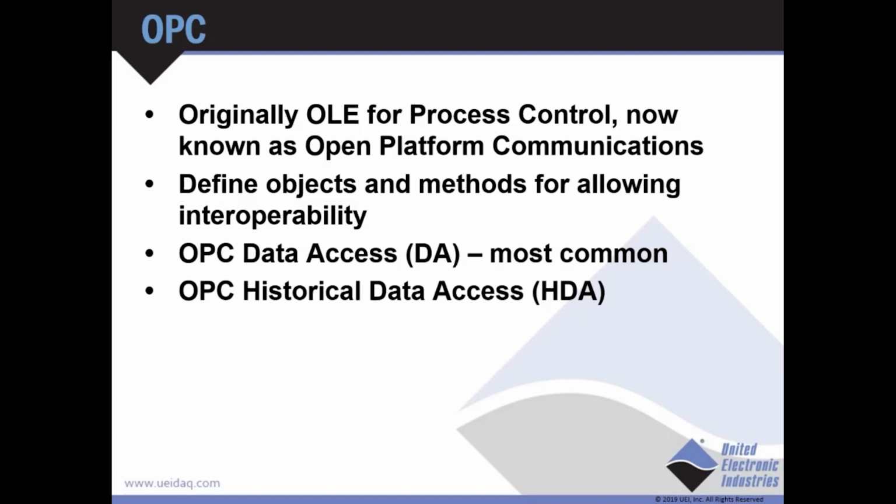And again, that's the most common. That's the way that you're going to get your data from the OPC server, from your OPC client. And we also have OPC Historical Data Access, and that's a way to see a trend of the data over a specific time period.